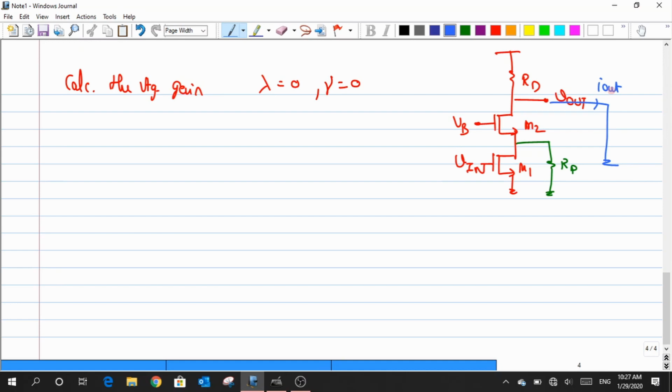Basically the current that flows through M2 is the one that is getting outputted, right? So if I am able to know what is the current that comes out across this M2, then my solution is done. So basically what I'm trying to say is that I have this Vin and I have this source that is connected here. I have this VGS with this polarity, due to which I have this GM1 Vin, and there is an external resistance connected to the drain.